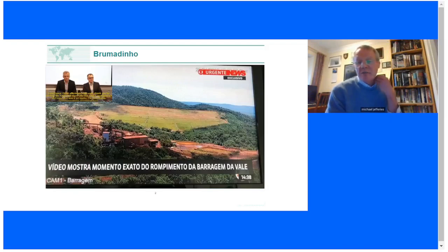Now, to cut to the chase, I'm going to show you two videos. I'm going to run a little bit of this video here, which most of you have seen before. You'll see the failure initiate top right of the dam. What I'd like you all to do is, when you see it initiate, start counting down the seconds as you watch the failure propagate. The message I'm trying to get you to pick up from watching the video is the speed of propagation. Now remember, when we start rolling this video, the piezometers are showing no excess pore pressure at all.